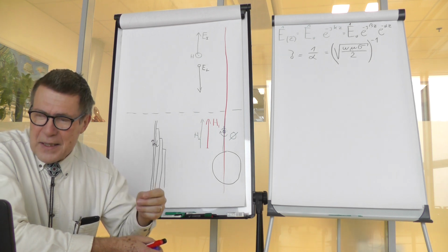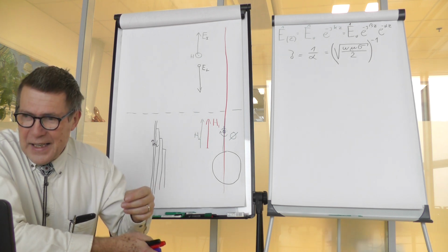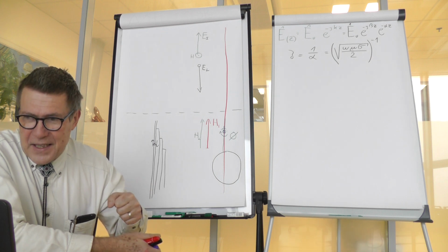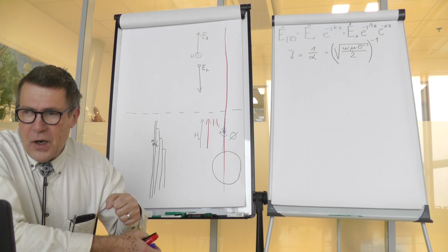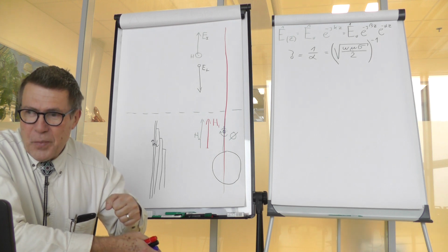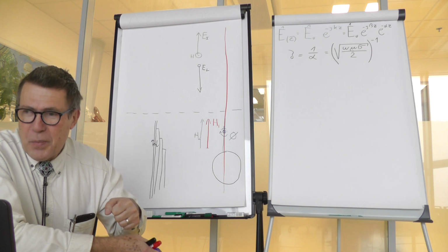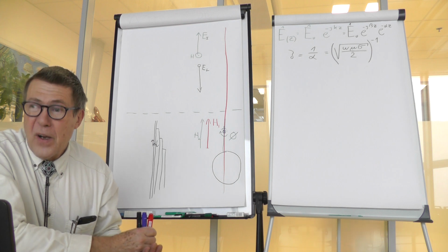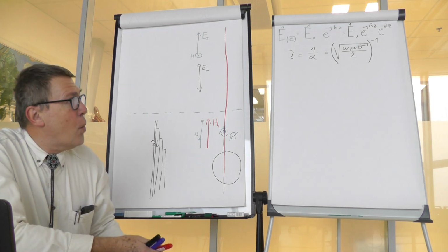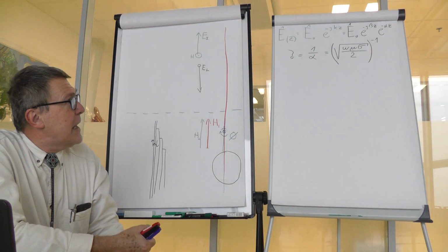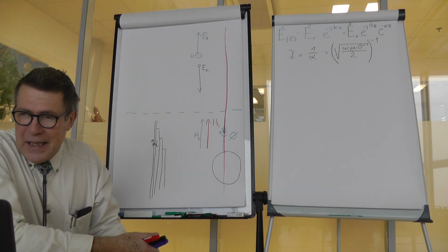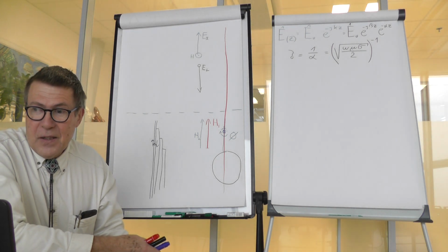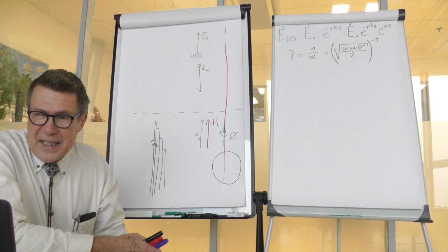But then the current density would be very high at this skin depth, and as the losses are a quadratic function of current density, there would be a lot of loss and the conductor would be destroyed. And at the same time, you would have a lot of losses. So we have a problem which is a problem with skin depth, at least in conductors. The problem is specifically seen at high frequencies.